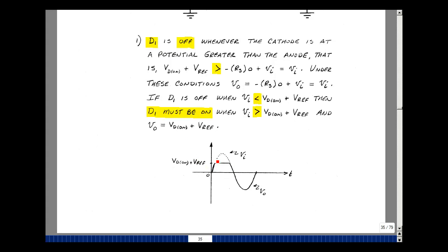In electronics, we ultimately are going to design circuits. So what I try to do is to take a circuit and describe it with a word description. We can think of this when we want to put circuits together to make a design. In fact, we'll do that in this chapter. This circuit clips off everything above this voltage. This is what we call a positive clipping circuit. It's like you had a pair of scissors and everything above the scissors is just cut off. We're clamping the output with that diode voltage and then the value of the reference voltage.